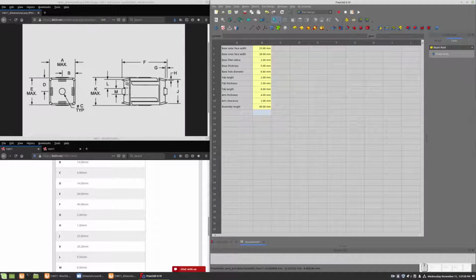And then we also know that there's a tab height. So basically, if we take half of f and then we subtract off the tab height and we subtract off the clearance and we subtract off the radius of the curved part, that should be the thickness of this base.